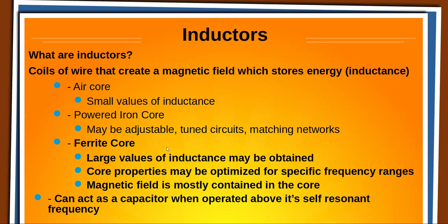And the reason for using something like a ferrite or powdered iron core, particularly a toroid, is that you maintain the magnetic field almost entirely within the coil itself. So you can have them adjacent to one another and there's not much mutual interaction. If those were air core, then you'd have to be very careful, put them at right angles, things like that.